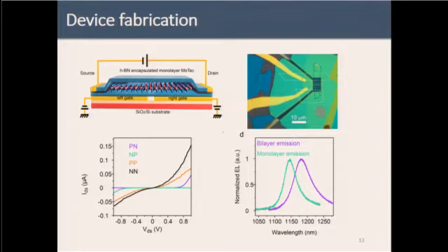Here I'm showing the real device microscopic image. Within the dark dashed line is molybdenum ditelluride, these squares are the electrodes, and the white dashed lines are the few-layer graphite source and drain leads. Here we were not using metals to contact this material directly, but graphene, because they make nice contact and are well sealed.